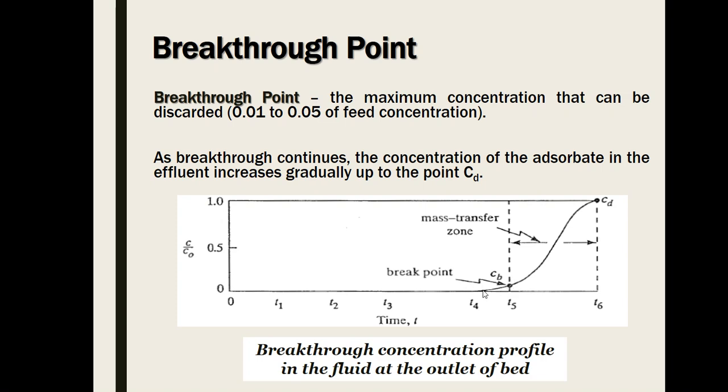So this particular breaking point is the starting point wherein we observe this particular concentration of your fluid. So meaning your bed is already exhausted and it cannot anymore adsorb the remaining amount of solute in the fluid. So it's ready to be discarded. The maximum concentration that can be discarded. So that starts on the break point.